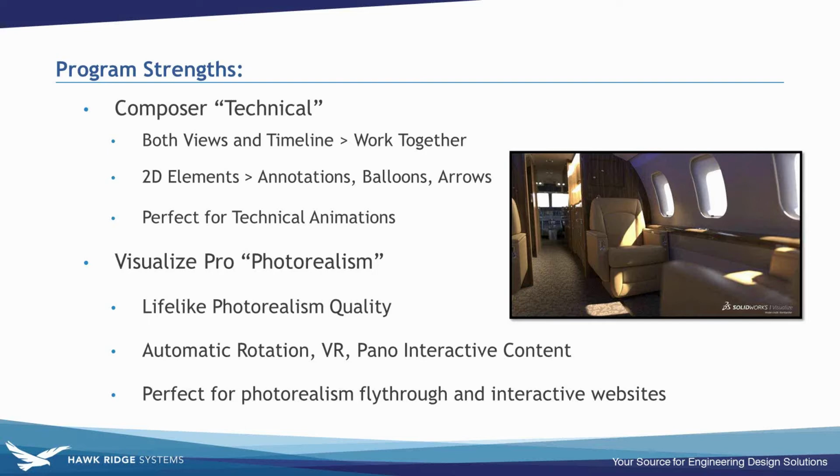So you can do full work instructions if you wanted to, but you don't have the benefit in Visualize of the views. You have strictly a timeline to work in, and if you've ever worked in the timeline, it is more difficult to work in because you have to make sure, and I'll show this in the software, we gotta lock down the camera before you move it. You gotta lock down these parts before you move it, that sort of thing. For Composer, you don't have to worry about that. So that's kind of the differences between the two, and it really is because they're made for two separate purposes.